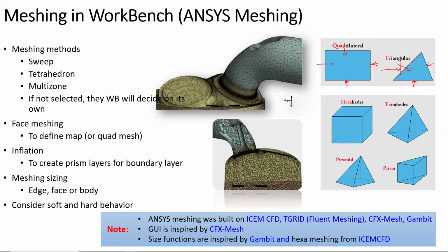So definitely we will be having some errors on those phases. Those errors, when they combine together, sometimes may lead to divergence or large errors in the solution. So we always try to avoid the triangular mesh. But the problem is that quad elements cannot fit very well to the geometry.